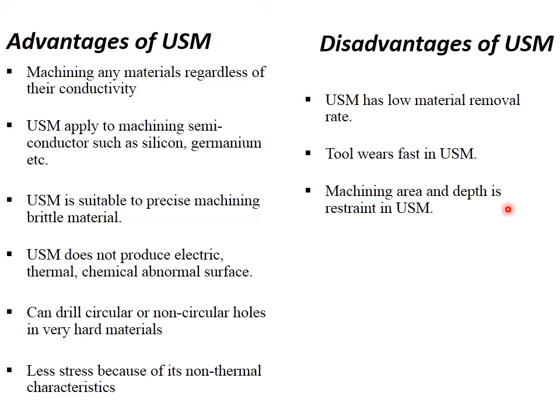And the second one is the machining area. The depth is restrained, because we cannot control the depth, because here the material is removed through abrasive slurries, right? Not by the tool. And also the area is limited depending on the size of the tool we use. So these two things restrict USM when you are looking for a higher MRR.